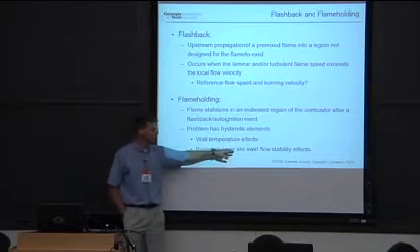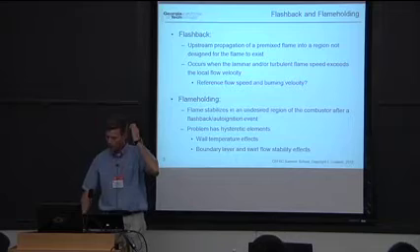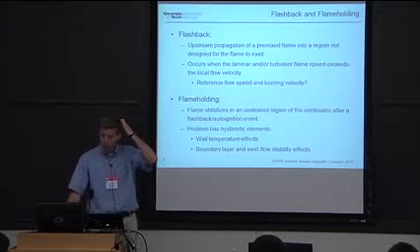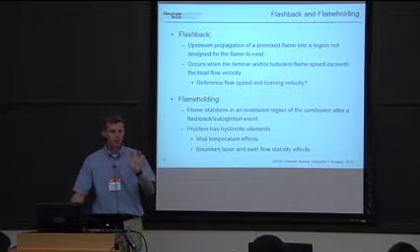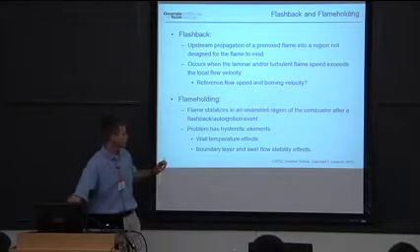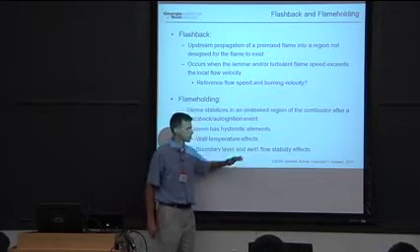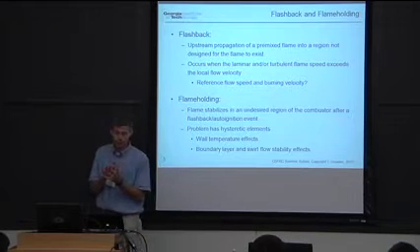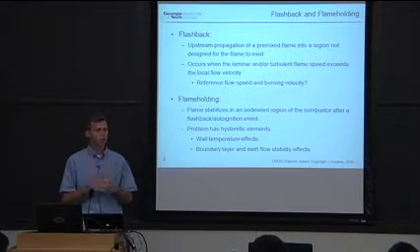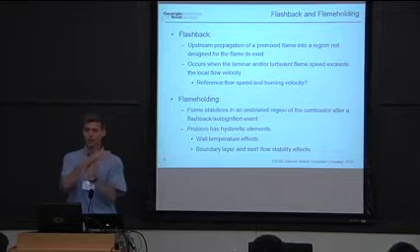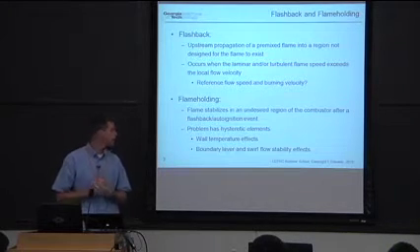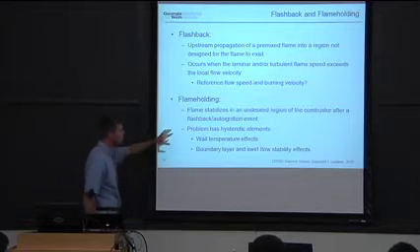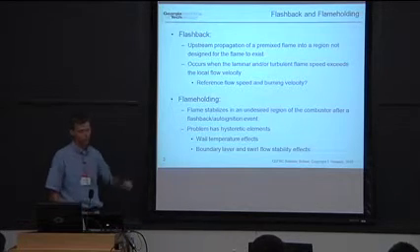This is really a fluid mechanics problem. It turns out that flames propagating in boundary layers like to make boundary layers separate. Flames in swirl flows, and I'll talk about swirl flows a little bit because I'll assume people are less familiar with those. Swirl flows have these interesting hydrodynamic instabilities which also have hysteretic elements, and the flame can kick you from one side to the other of the two branches of your solution. So again, flame holding is a much more severe criterion.